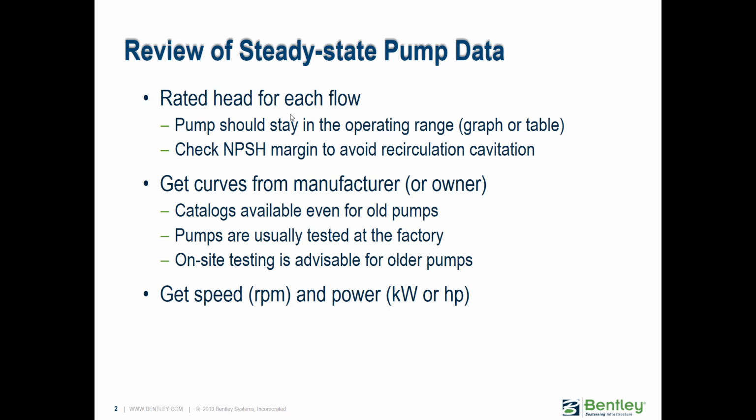As far as where you get the information on pumps, usually you get that from the manufacturer. There's usually some catalogs available even for older pumps, and usually they're tested in a factory, so the data is usually pretty good. Obviously, if the pump is older and may not be performing as it was when it was first installed, you might have to do some on-site testing with some meters, to make sure you're properly representing the pump. If you don't do that and you assume it's using data from a catalog, then you may be modeling something that's not really the way it's going to operate in the field.